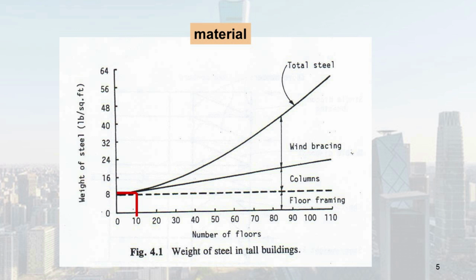A 10 storey building can usually accommodate wind loading without any increase in the weight of steel or member sizes. On the other hand, for buildings of more than 10 stories, the additional resistance increases non-linearly with height. That means, for buildings of 50 stories and more, the selection of an appropriate structural form may be critical for the economy, and indeed the viability, of the building.